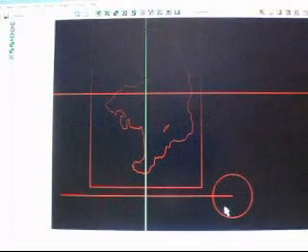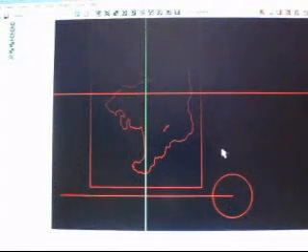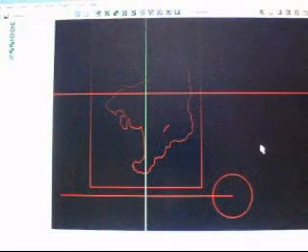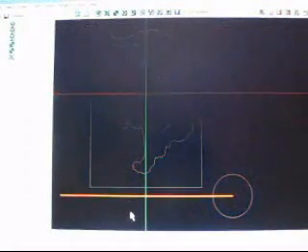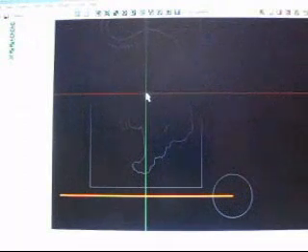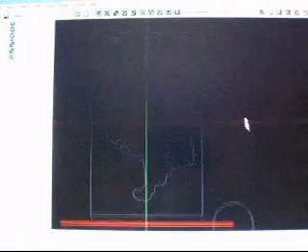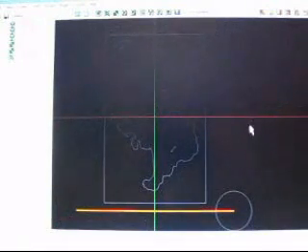Now with a tool this big, you definitely do not want to plunge directly into the part. You want to face this off, but you want to mill it. You don't want to plunge cut at all with a big facing mill, okay? So what I've done here is I've drawn a line that will keep that tool off the part. So I'm going to go from my home position to a position which will actually be up here relative to this line.